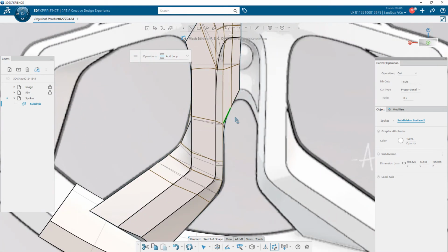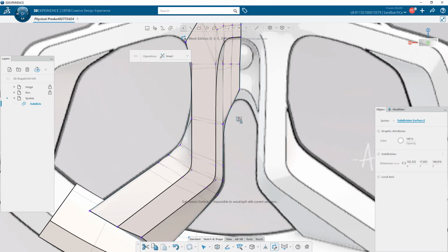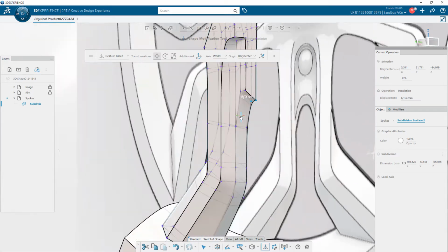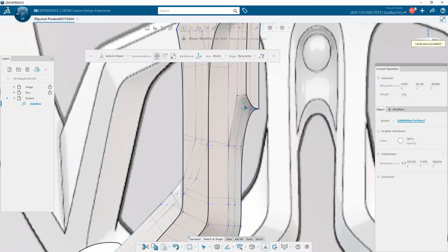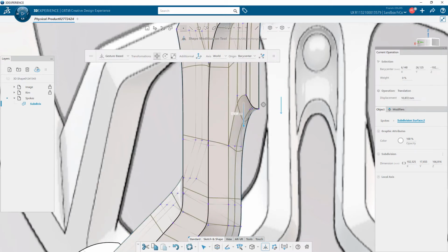To create the bevel on the bottom of the lug holes, I use the Insert loop and move different vertices. I need to move and align some vertices. To align the vertices on another, I start to move a vertex in the direction I want. And to align, I press the Shift key and point with my mouse at the targeted vertex.